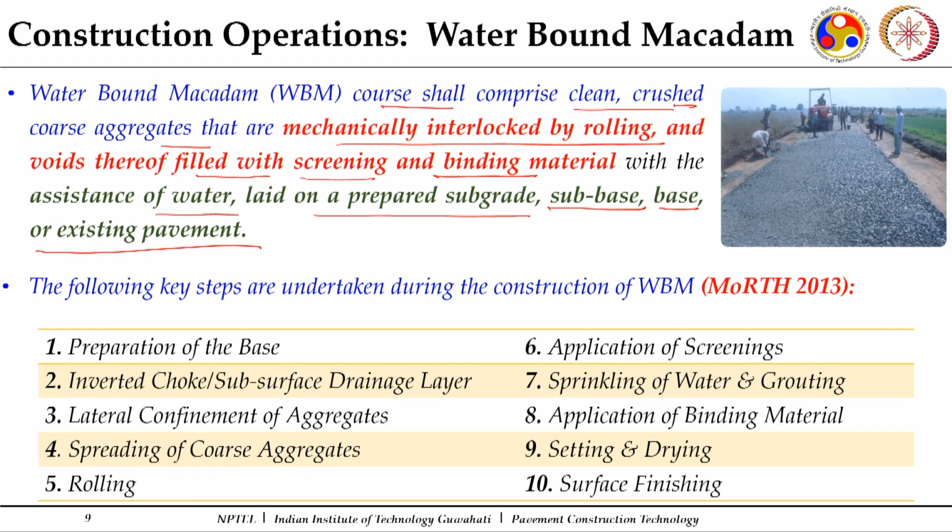So, there may be some existing bituminous surface over which you may have to construct the water-bound macadam course. For those cases where the existing is a bituminous top, certain precautions have to be taken. We will discuss in the upcoming slides. Otherwise, mostly it is preferred as a base course. So, it will be constructed over a prepared sub-base course.